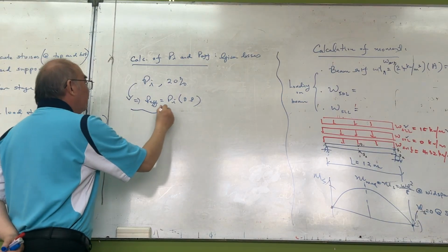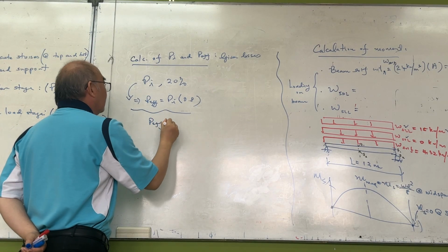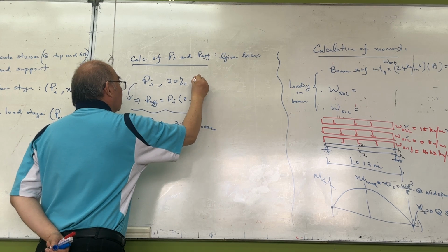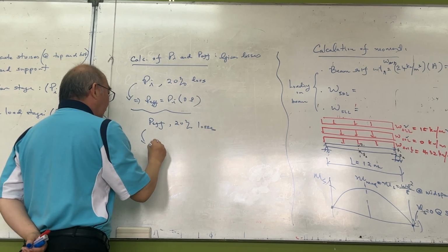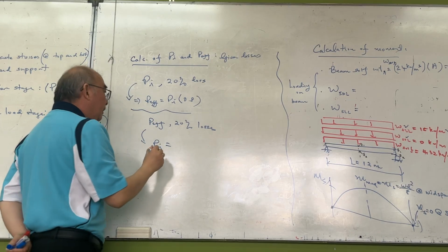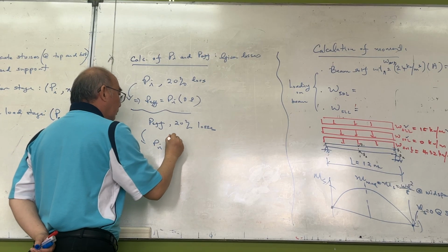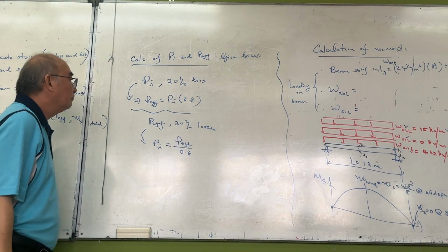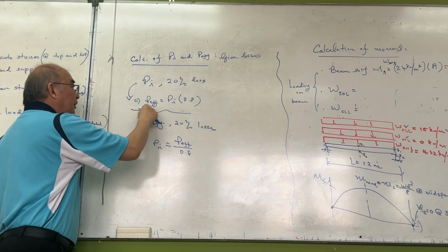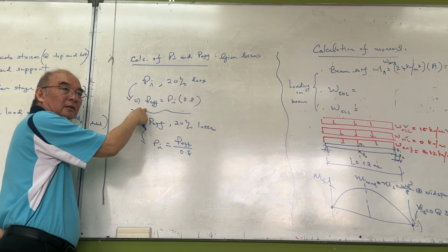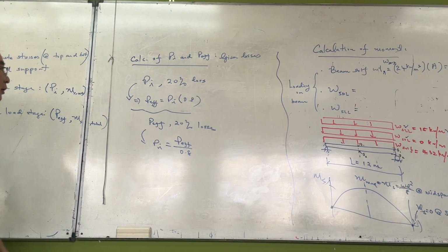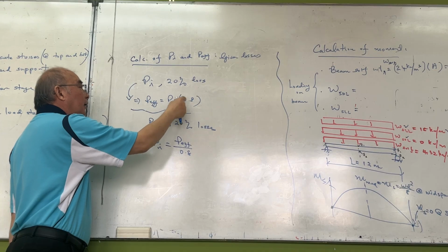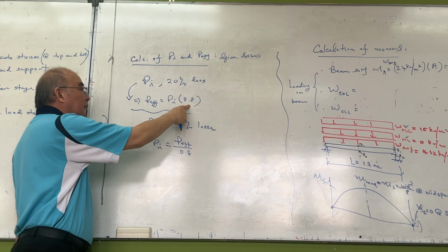Now I can also give you P effective and 20% losses, then you calculate PI. So PI will be P effective divided by 0.8. You need to be careful: if I give you PI and losses, then P effective is PI multiplied by 0.8.